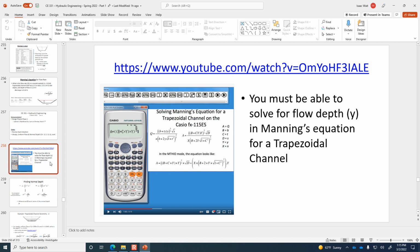And what makes it tricky is if you have a trapezoidal channel, which is a lot of the time. The reason why trapezoidal channels are so common compared to rectangular channels is it's hard to maintain a vertical slope if you've got natural soil.